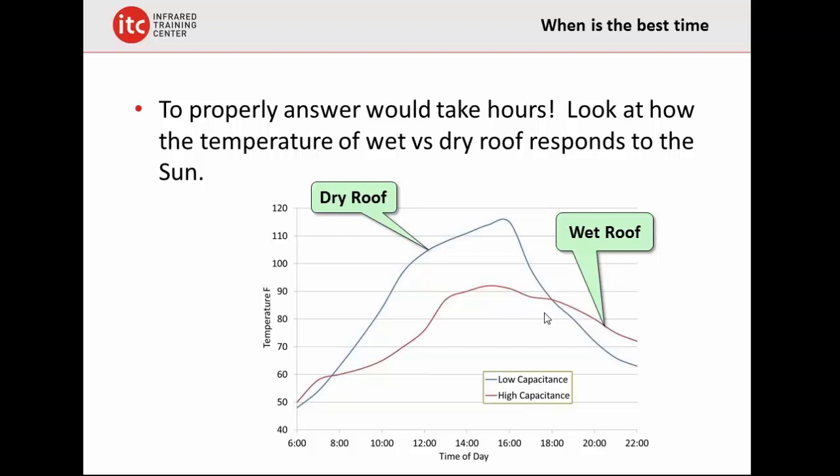There's such a large delta T there, midday, early afternoon. Why don't you do roof inspections at that time? Glare. It's too much solar loading. Is it solar loading, glare, shadow, and particularly shadows from HVAC units? Yeah, because those are all going to be in shade, and they're not going to be in the sun. And great point. If you have water behind there, you're never going to see it.